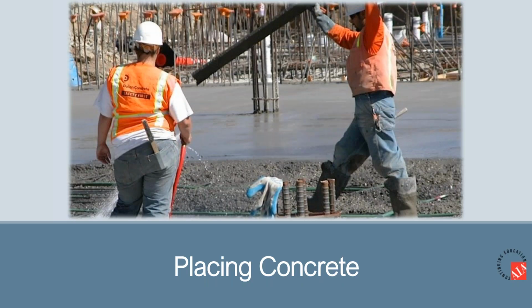So then we go to the day of placing, right? We understand our process. We've developed a good specification. We want to ensure the highest quality possible. We're using an underslab vapor retarder. If you look at this picture, we're even using epoxy-coated rebar because we want to make sure our concrete lasts as long as possible. But we have a person with a water hose over here spraying water.